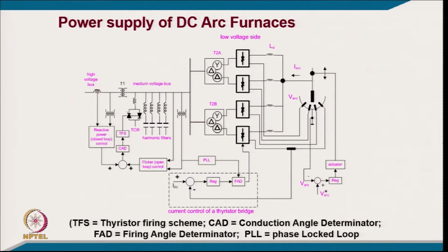So, if you look here, we have the converter with transformer isolation, having a 24 pulse converter, and this is with control, because even with a 24 pulse converter we are using the thyristor, it requires reactive power, and the harmonics are also there. So, for that we normally use a passive filter.